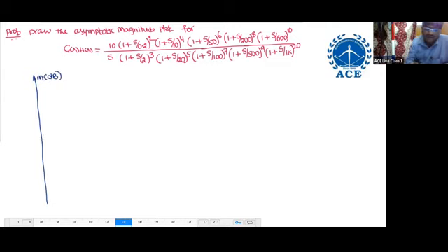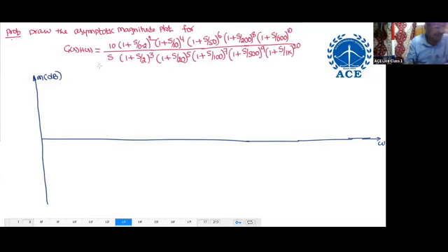All right, draw it. Calculate M initial. Tell me, at where I have to calculate the magnitude. The first corner frequency is 0.2, so I need to calculate the magnitude at 0.01, because 0.2 divided by 10 is 0.02, which should not be the middle, so 0.01. So 20 log K, K is 10, plus 20 log 1 by omega.